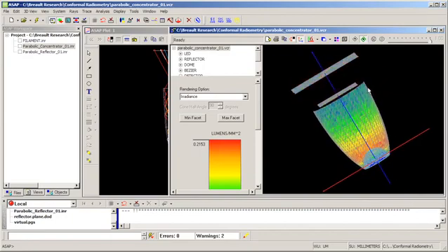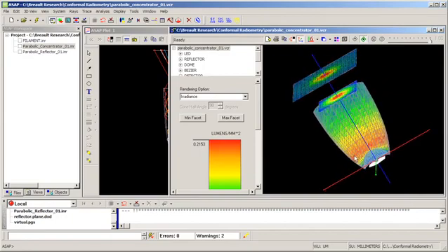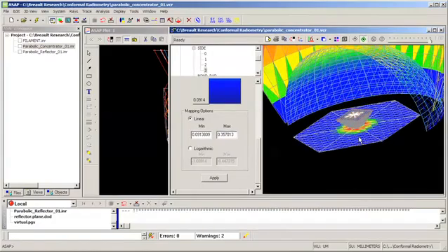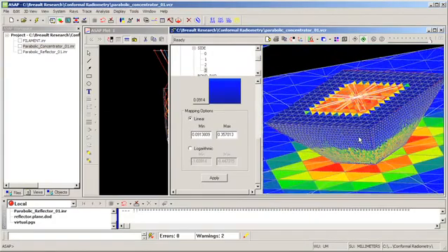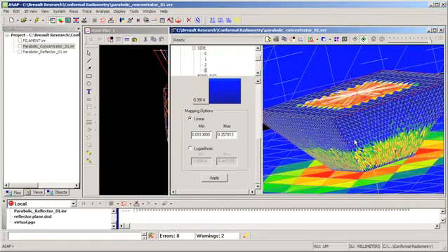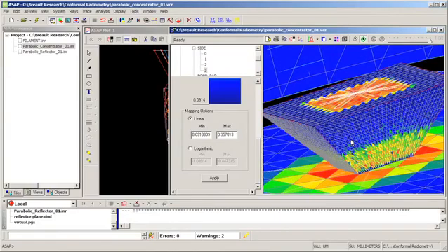Now if we look at our CPC, we can qualitatively see that virtually all of the energy coming from the LED die has struck the CPC interior surface at the edge toward the die, and we can see that we could very likely eliminate a certain portion of the length of the CPC without having any serious effects on system performance. Now if we zoom in on the LED die itself, we can see that we've actually mapped the initial radiance directly on the LED die surface, as well as on the bottom reflector sitting beneath the LED die.